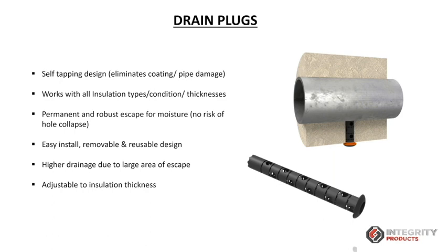And plus it's a robust design. It can sustain the system. It can drain the moisture. And even in the event of pipe vibration or anything, it's not going to misalign. And the third thing is that it's reusable. Since API 583 mentions the concern, achieving a rust-free drain hole is a maintenance nightmare. So with this one, we can remove this drain plug, clean it, blow it with dry air, and install it back. So it's a multiple-time reusable product. That is the added benefit.